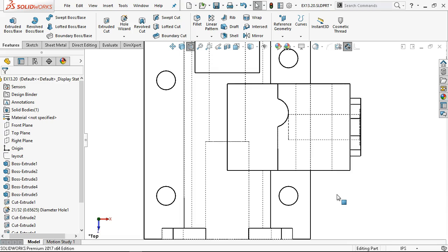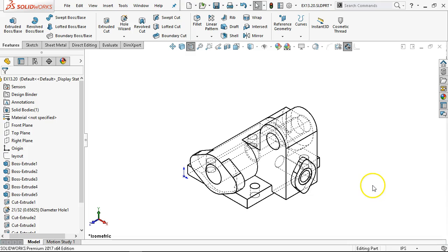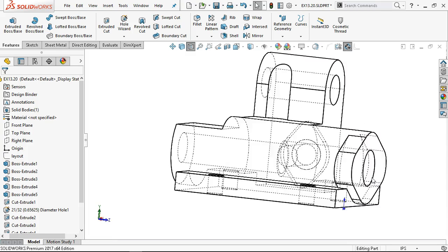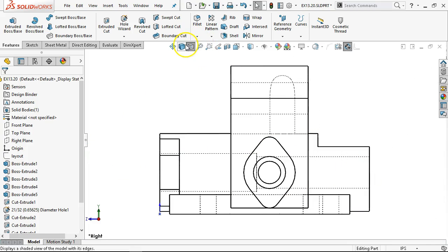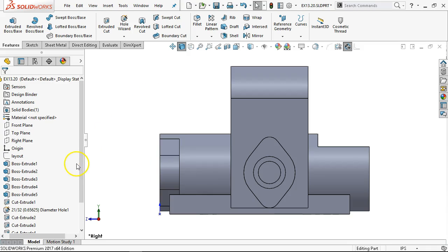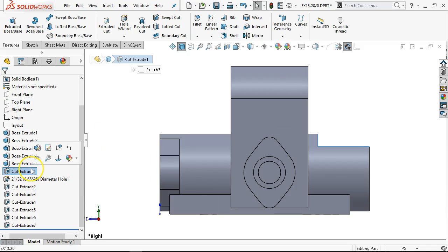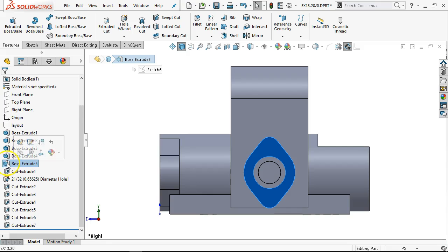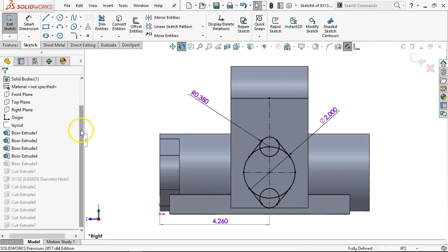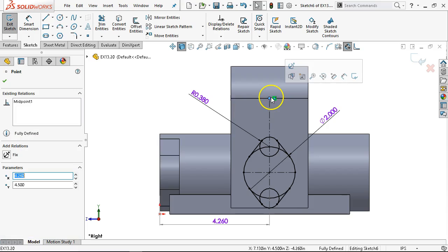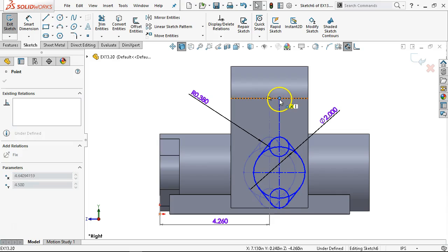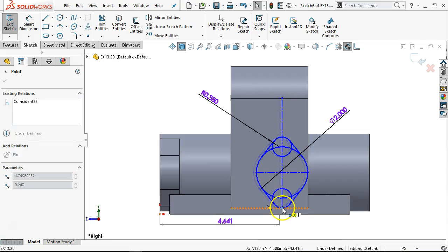And we had tangent, but we didn't get to center line. So there's another error that I made in the process of making those couple of assumptions. Let's go back to the boss. I edit the sketch. We're going to find the one with the midpoint. All right, so there's the relation for the midpoint, relation for another midpoint.